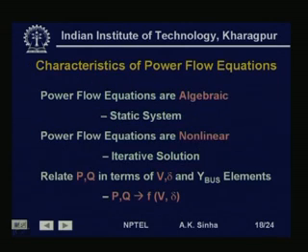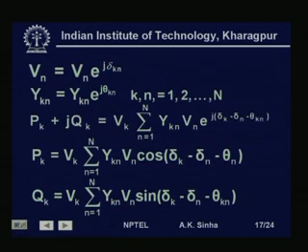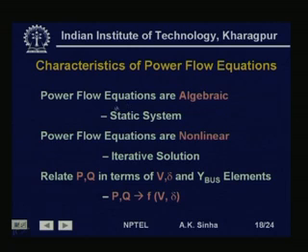So, let us see what the characteristics of these power flow equations are. Some of the important characteristics are that these power flow equations are algebraic equations. That is, if we see these equations, they are algebraic because there are no derivatives or differentials involved here. These are just algebraic equations because we are using a static system condition, so there are no differential equations involved.